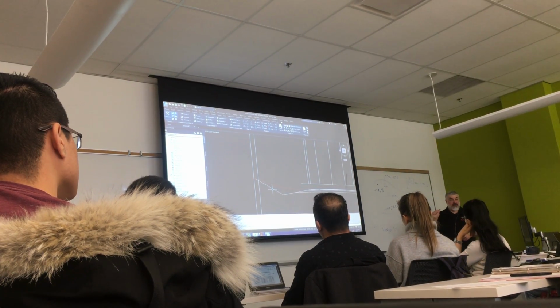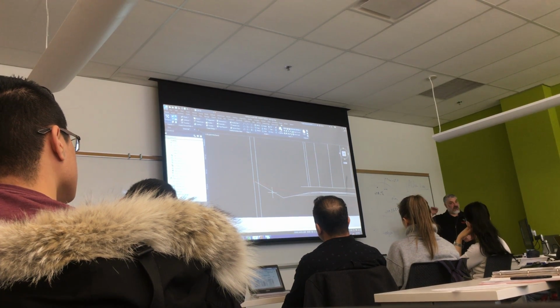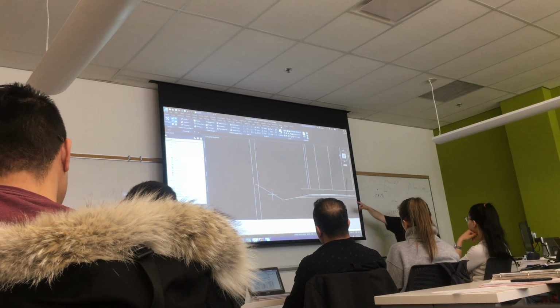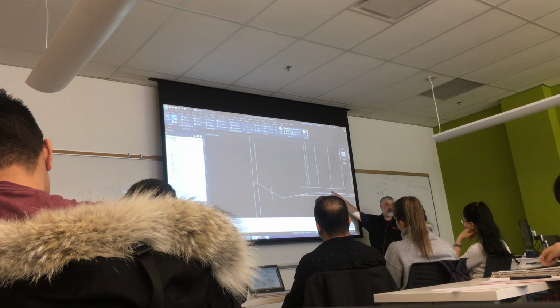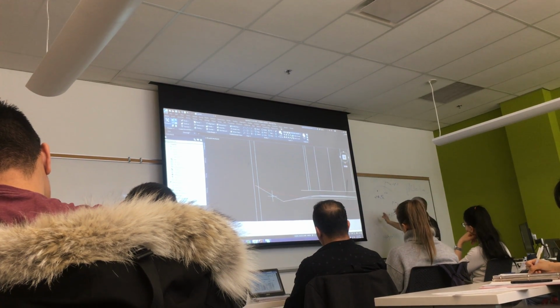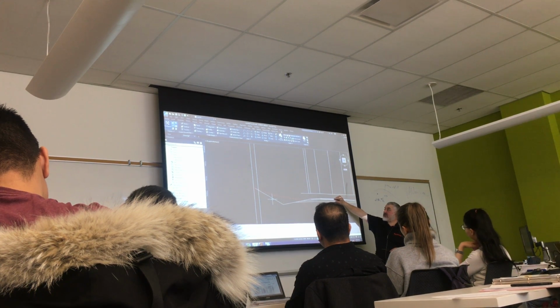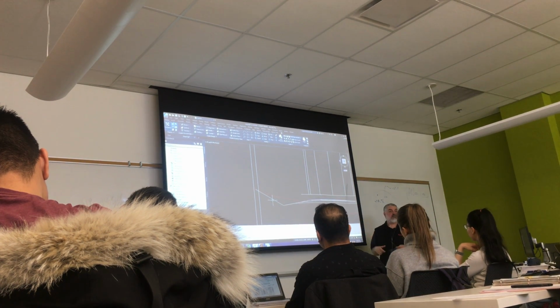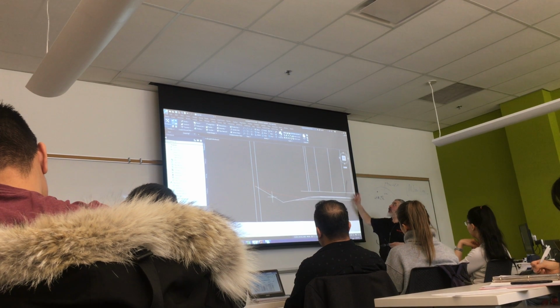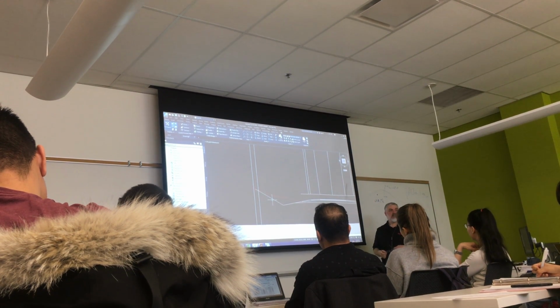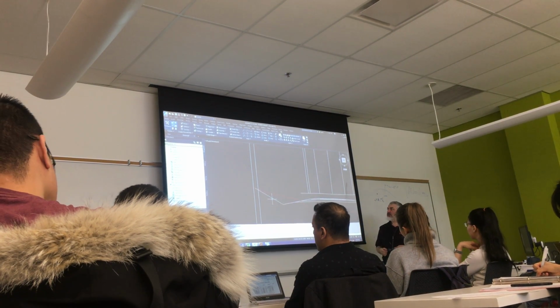So just to review very quickly, always draw the existing ground first. Find the crown of the road elevation, the design. Okay? How do you get that? From the profile. For homework, I'm going to give it to you. Draw all your different layer thicknesses based on the crossfalls of the typical section. Get all your widths from the section detail, whatever page applies.